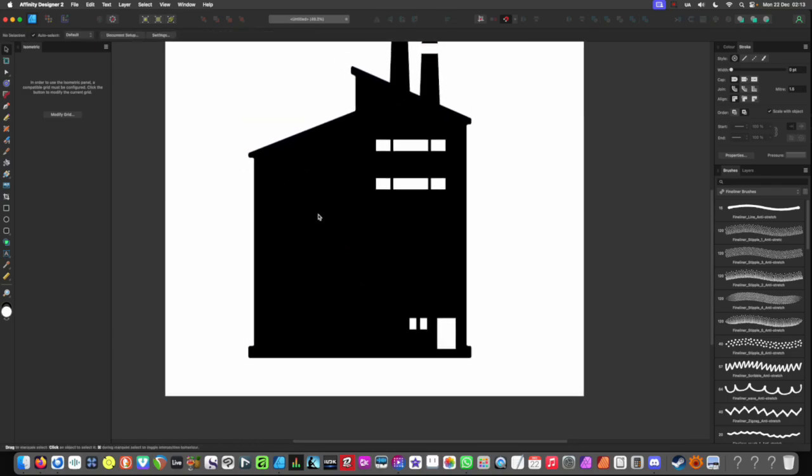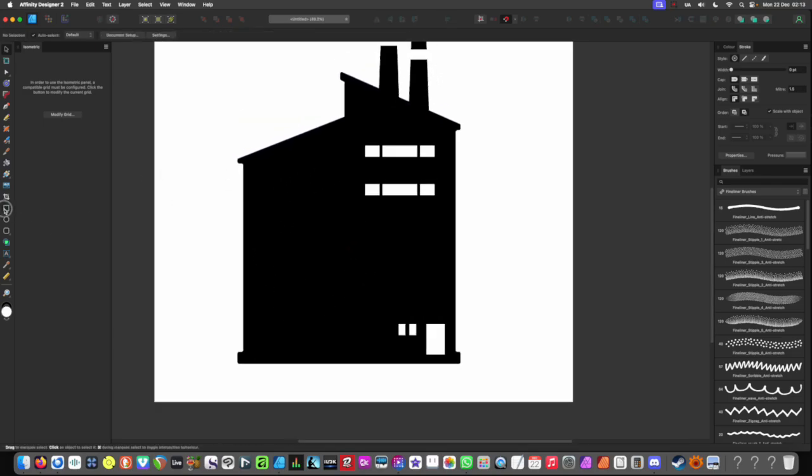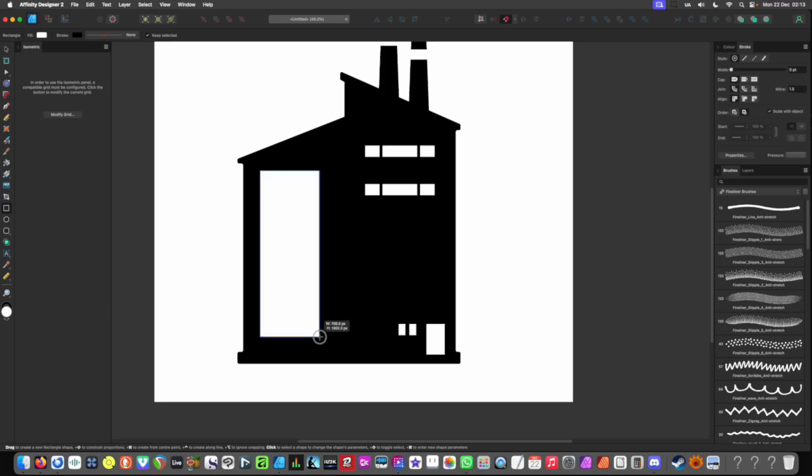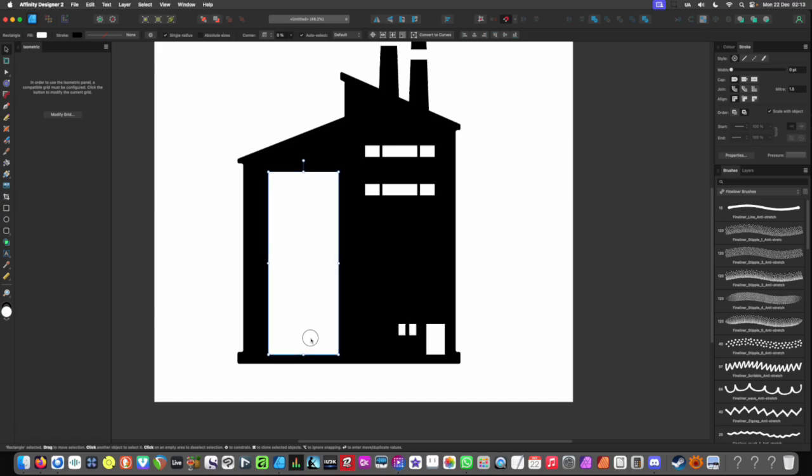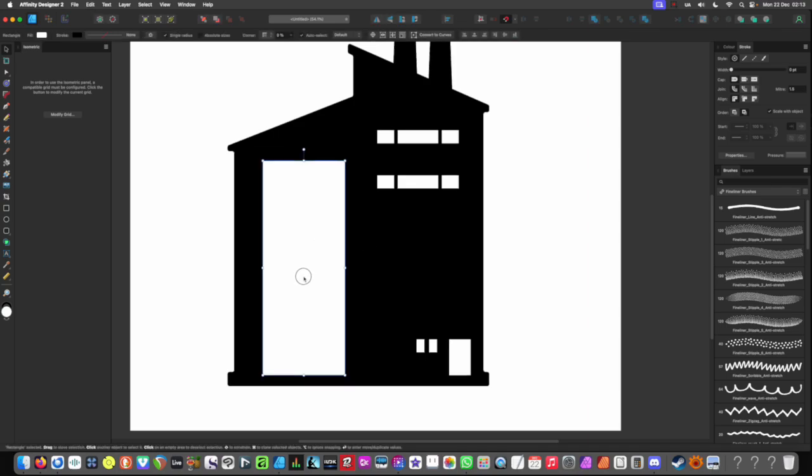And then I'll make a large industrial door here. I'm not too bothered. It could be like you could have a massive robot in here or something waiting to come out. So it could be one of those kind of strange hangars. Yeah, something like that. And I'm going to do the same approach for the door. I'll just boolean that out, and I'm just going to put in another rectangle, make it a bit smaller.